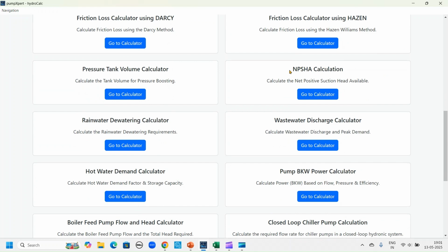The most important you can have is the NPSH available calculation, and I would request each one of you who are here to do this calculation for all your projects, be it positive suction or negative suction. Because if you don't take care of this, it is very expensive to correct it later. So that will be my advice, to use this NPSH calculation and be clear.